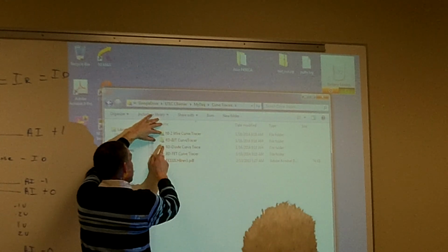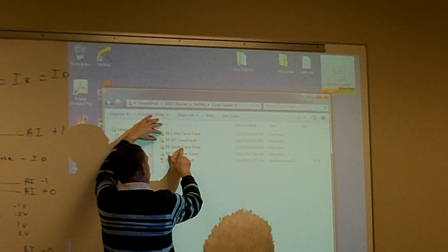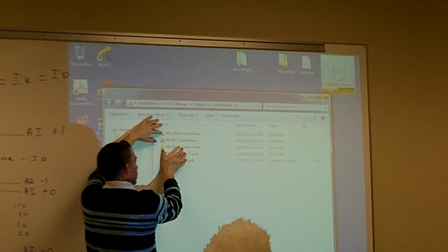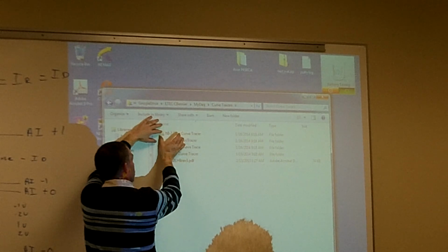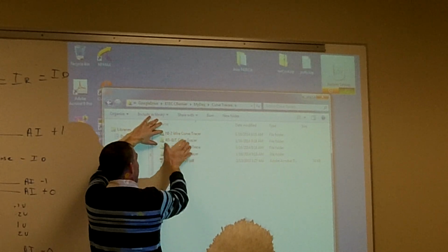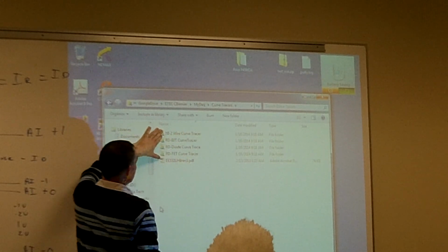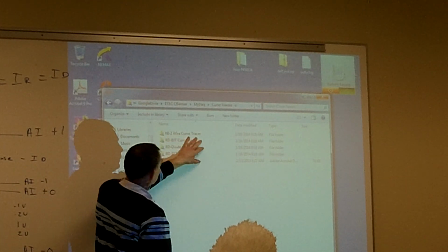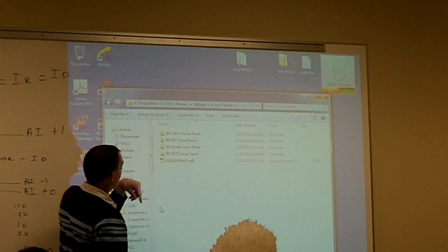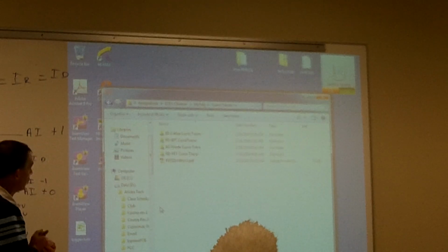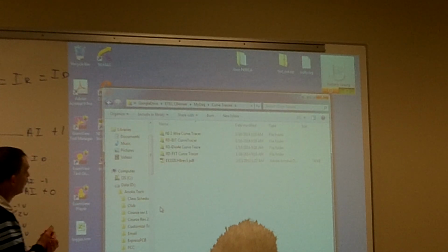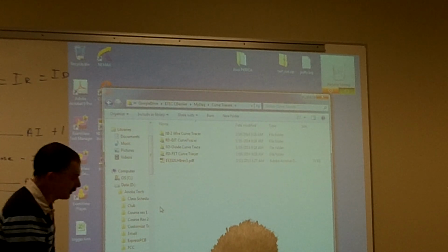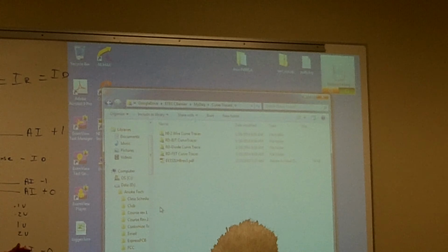That's the best one. This other diode curve tracer is okay, and it's good for checking your diodes, but it doesn't work as well as the NI one. These other ones are from another professor who developed them on his own, and we're going to use those for the transistors and the FETs, and his works really good for that. But for the 2-wire one, the NI one that comes with NI is the best.